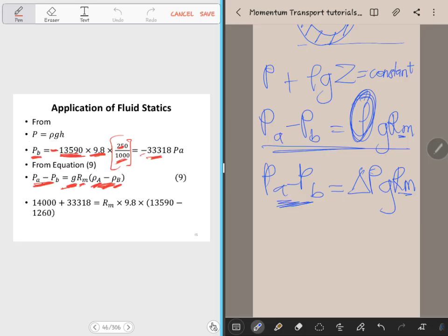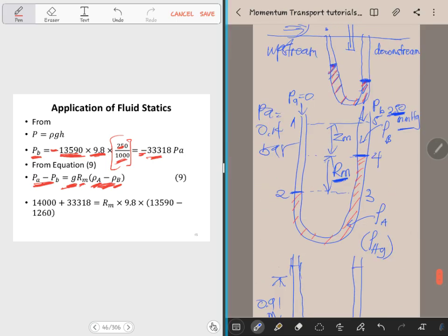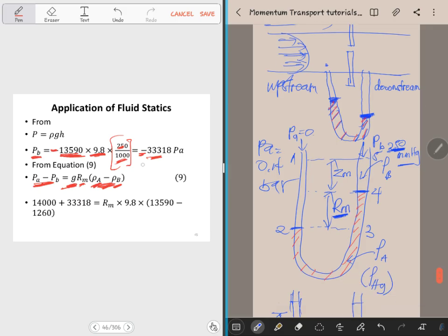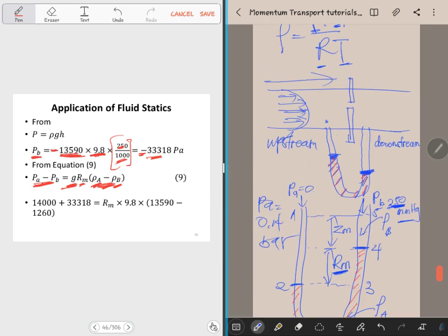So the negative here, I'm saying this again, is because the diagram goes in the opposite direction to the normal convention. Because there's a smaller orifice, a smaller area, we're expecting the pressure here to be higher, so it should be able to push the mercury down more than here, right? So that's why they brought this negative here. Should the diagram have been this way, there won't be any negative. The pressure we have will still be the same. You can try it out.